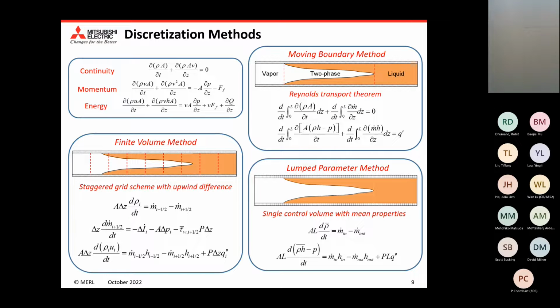But we do have switching schemes to switch between different model structures. However, there's a fatal disadvantage for this form: it cannot handle zero flow, because this method is based on the assumption that the refrigerant flows in at the inlet and leaves at the outlet.